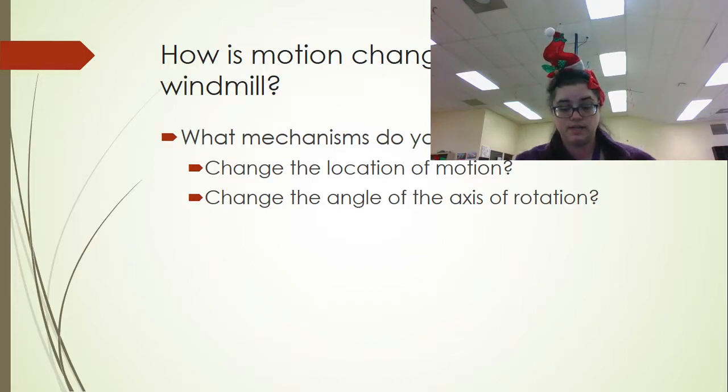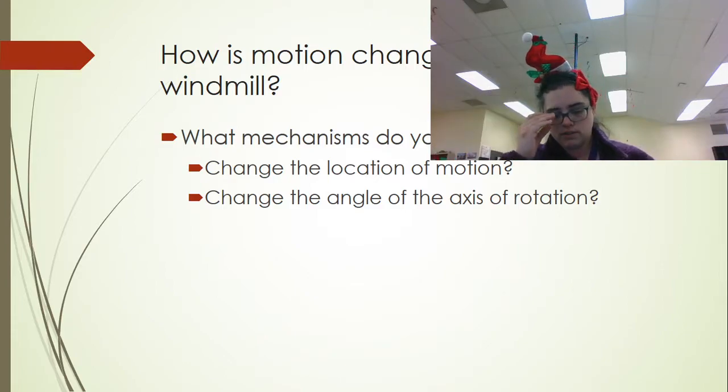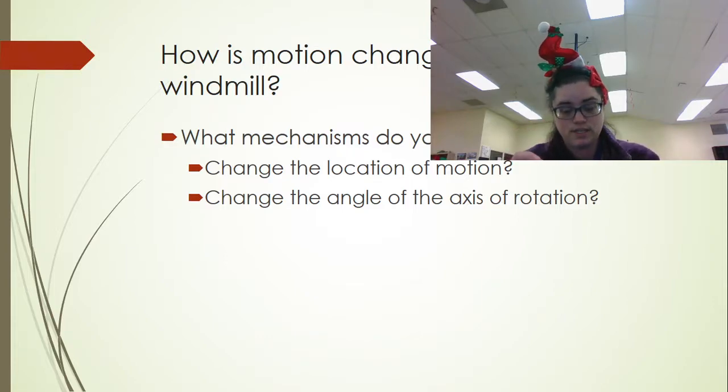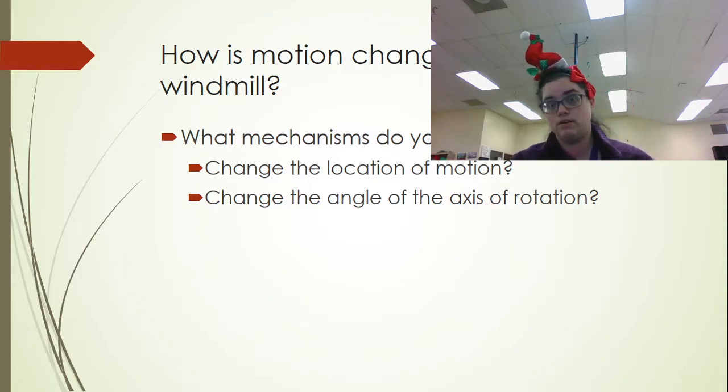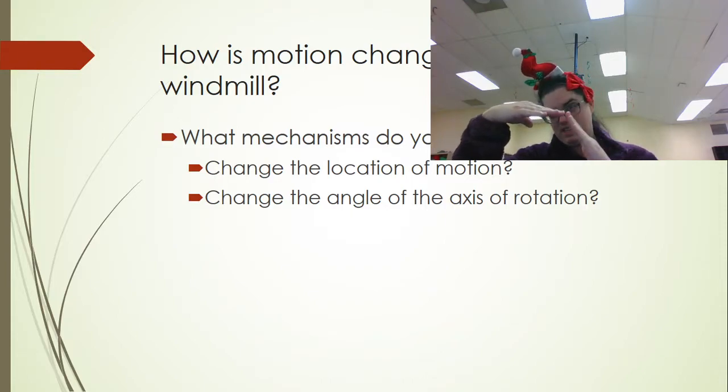Bevels are going to come together so their axes are kind of at a 90-degree angle. You could, I guess, technically use a universal joint if you don't need it to be exactly 90 degrees. But for a 90-degree angle, you're going to have a very specific kind of universal joint, quite possibly not the ones that we have in our kits, because they don't do 90-degree rotations or change motions.